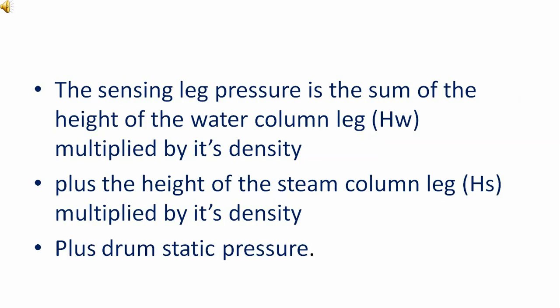The sensing leg pressure is the sum of the height of the water column leg h subscript w multiplied by its density, plus the height of the steam column leg h subscript s multiplied by its density, plus drum static pressure.